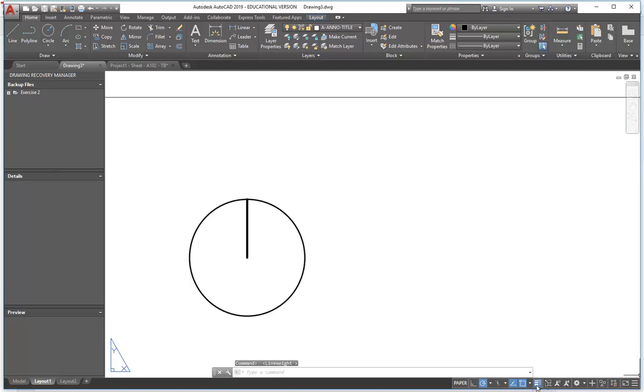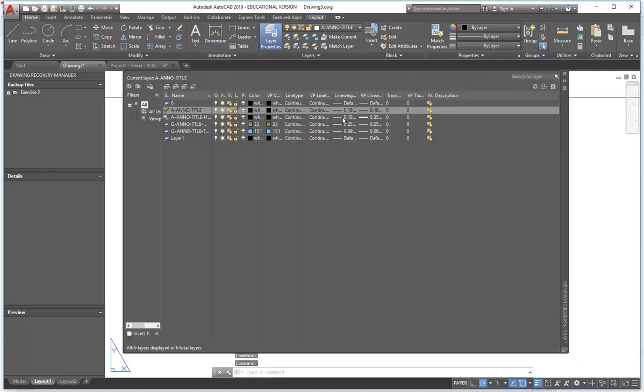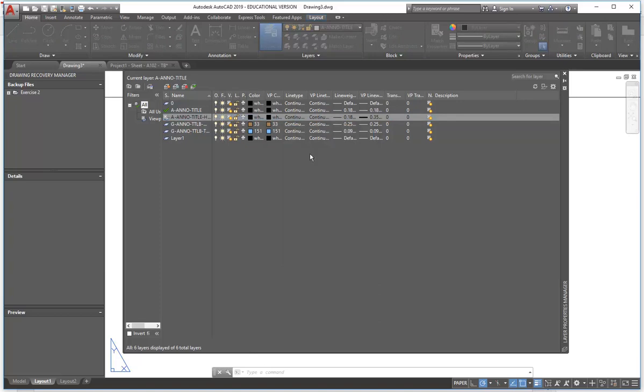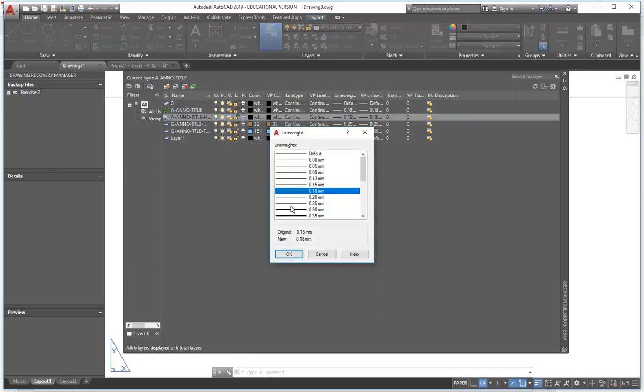And then you get this button here to turn on and see your line weights, and it does give you that slightly heavier line, which is a bit nicer. So we can make it even a bit heavier maybe. Oh no, I did viewport line weight, so that was a mistake. I'll put that back. You've got to make sure you're seeing it on screen, so I'll just come back to that.